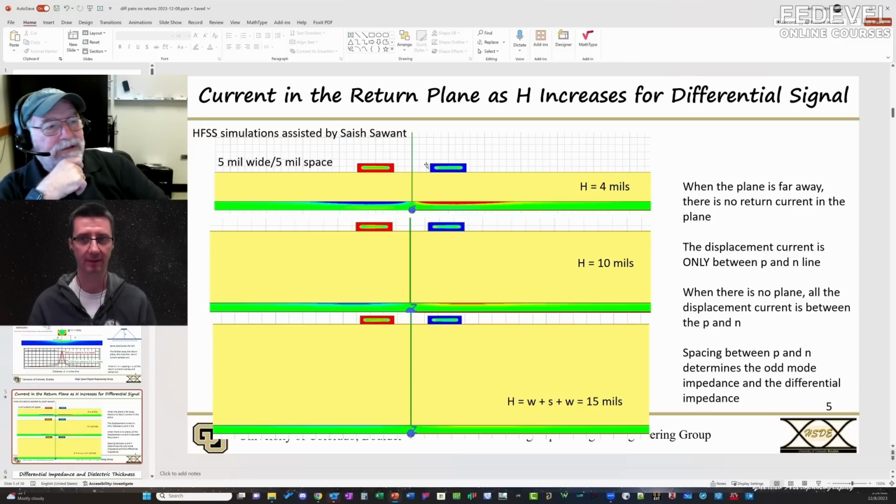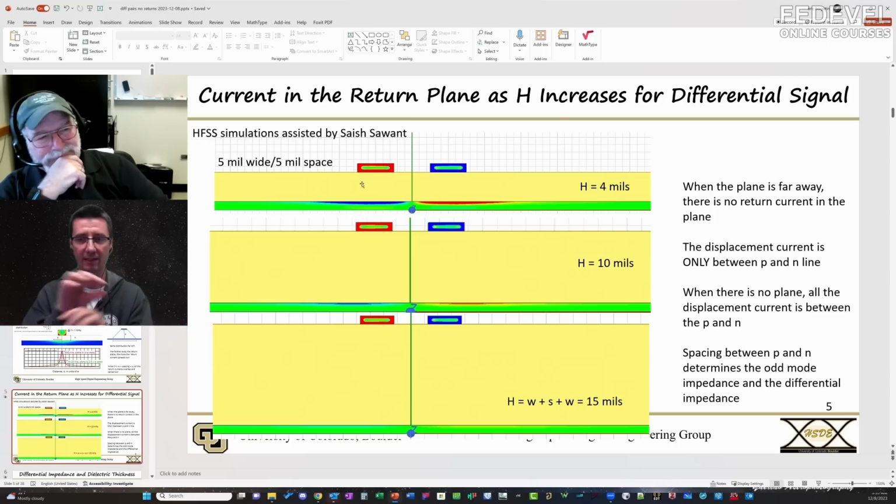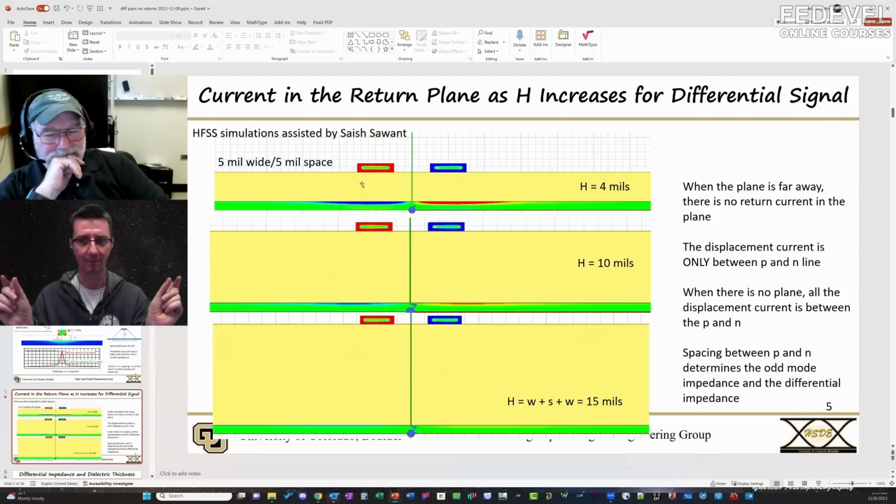Oh, what does it mean? They're close together. That's all. You can have 100 ohm impedance even when tracks are far away. You can have 100 ohm impedance even when they are closer. So what is the difference? Is the effect going to be bigger between them when they are closer? These are the tightly coupled, these are the loosely coupled, I think, correct?